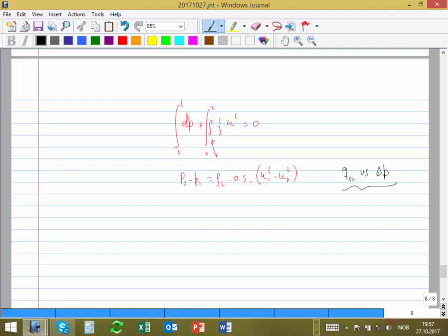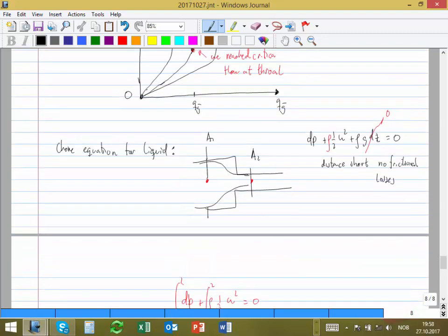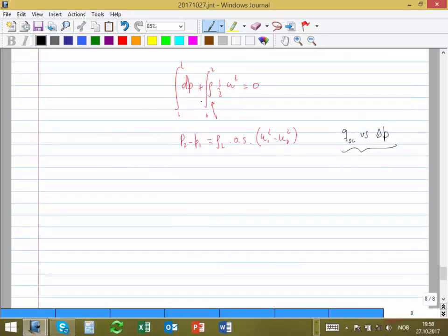So I want to have a rate, but a very easy place to measure the rate is upstream, here, because I know that the fluid is occupying the whole cross section. Here, due to this vena contracta issue, it is occupying only a fraction. So I'm going to make a mass balance. Remember, all the time we use momentum balance, and we also use mass balance.